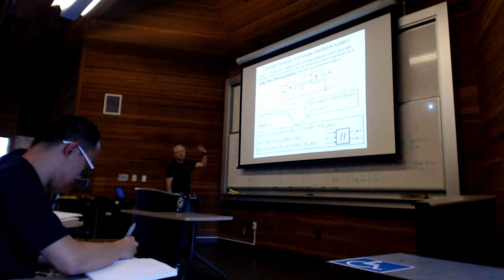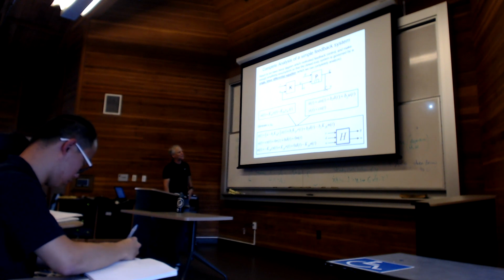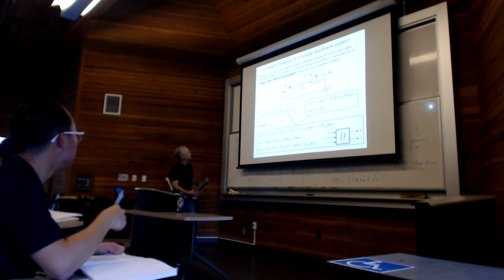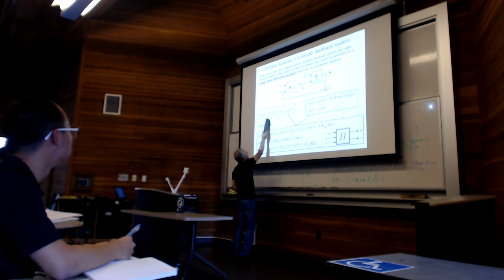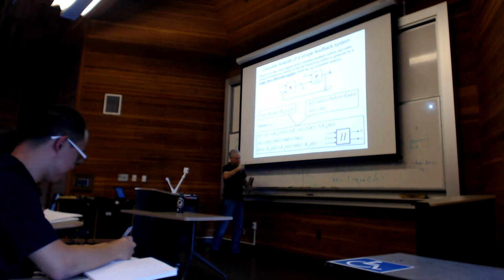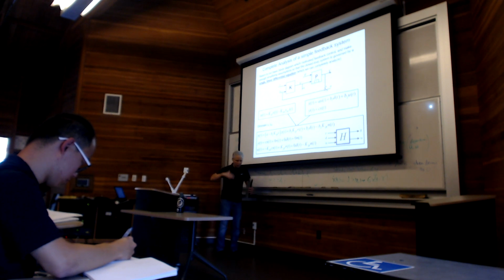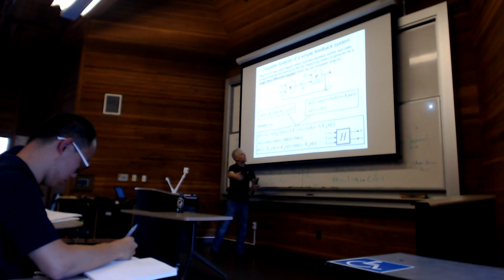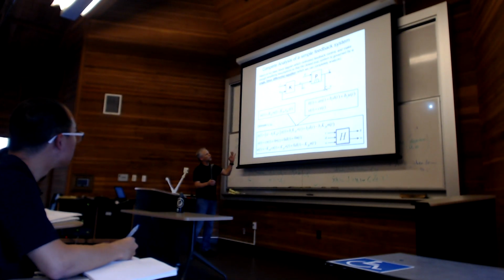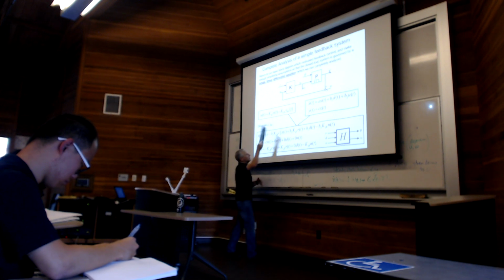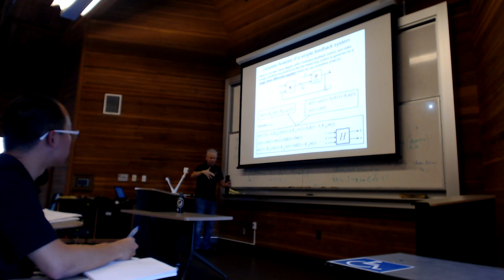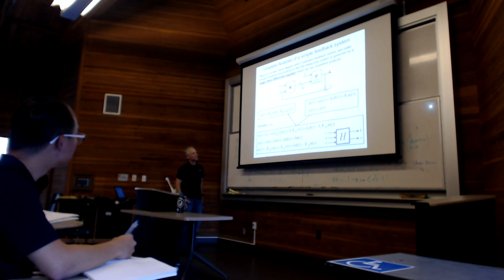And then the controller, since we can't afford a differential equation in there yet mathematically, will just be what we call prop 2D, proportional but with two different numbers. So u coming out of the controller will be some number kff times r. That's part of our strategy. We take whatever r is, multiply it by kff, minus some other number kfb times what we're measuring. So the controller is parameterized by two numbers in this formula. That's the corrective strategy: look at what you want, look at what you're getting, combine them, and spit that out as the u to the process.